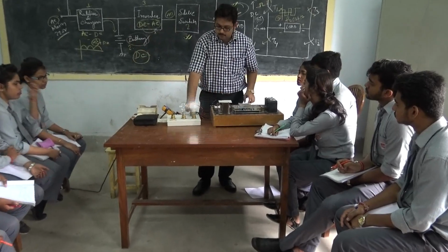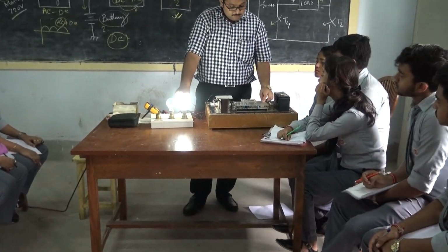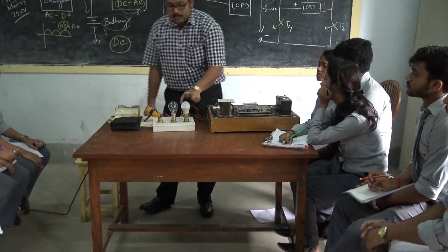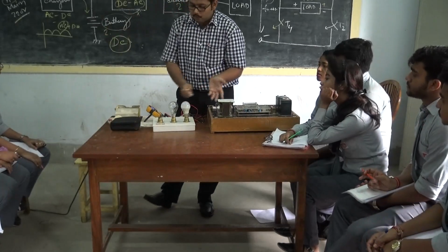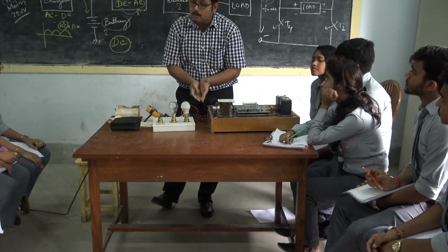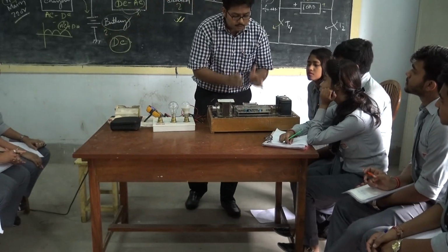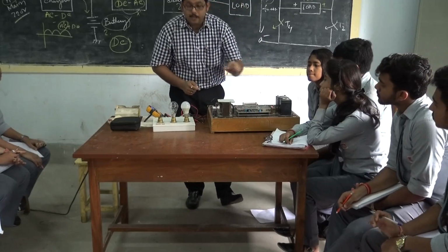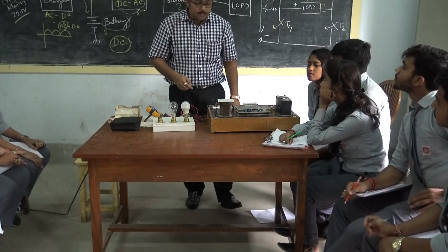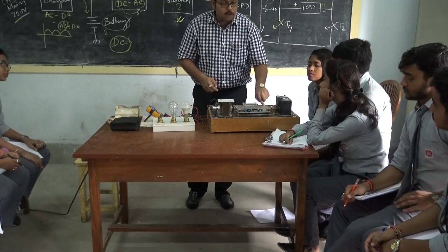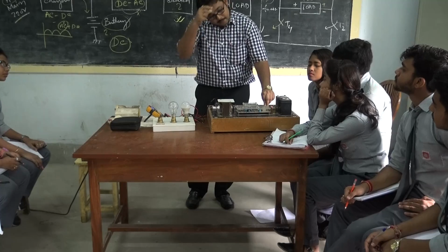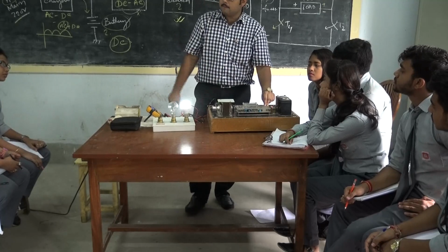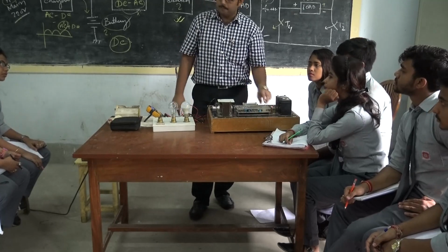Just think, in main mode this is on, but whenever we switch off the main mode, then the output will not glow because 220 volt is not available. Why not available? Because the inverter circuit is not working. Why not working? Because the gate pulse to the MOSFET has disappeared. Why? Because we made this fault by pressing this switch. Okay. Whenever we reset the switch, then the AC power is available at the output side.